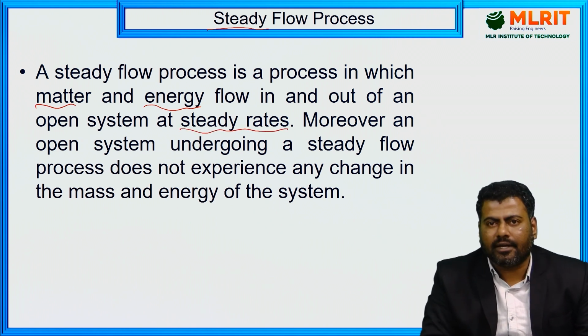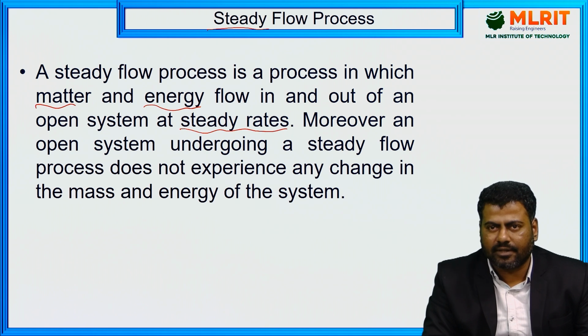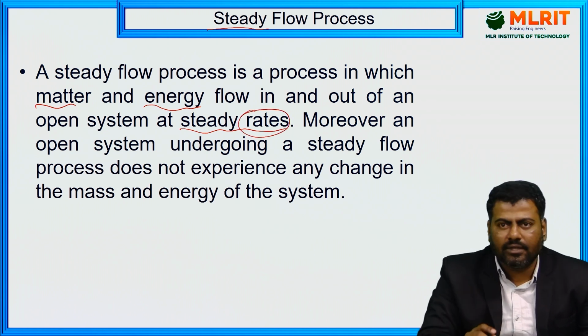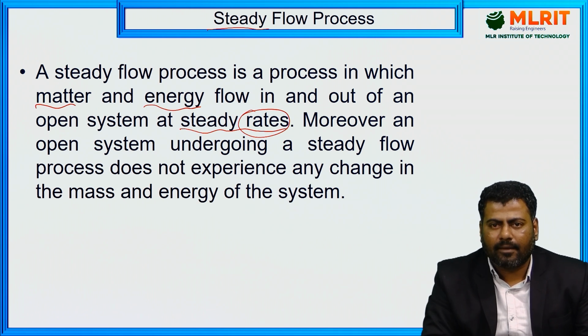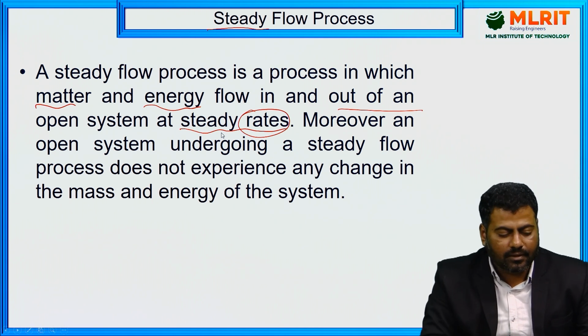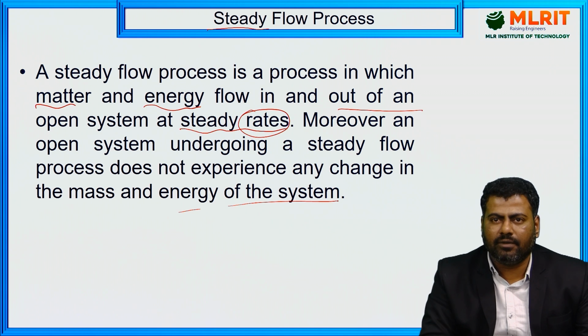At steady rates. So wherever steady rates are given, for example, mass flow rate, steady mass flow rate, steady discharge rate, wherever I mention a rate, that is with respect to the time taken. Moreover, an open system undergoing a steady flow process does not experience any change in the mass and the energy of the system. So this is for simplification actually.